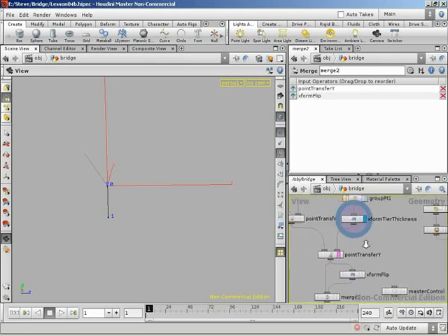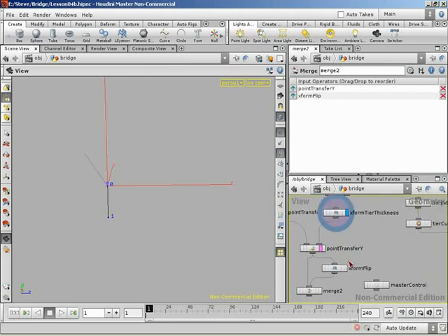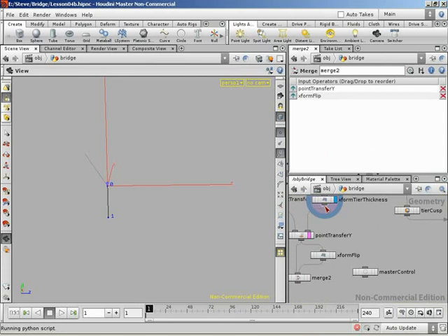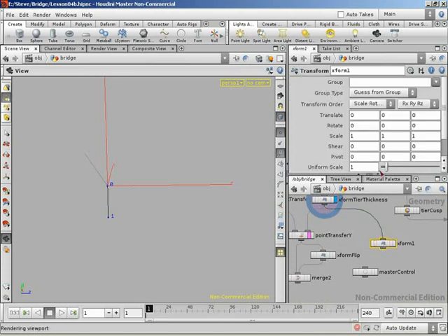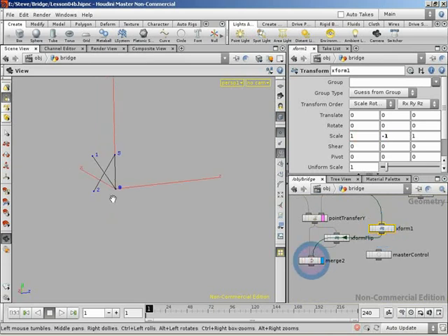So, yeah, this curve is actually going to work perfect for that end curve we needed, and he was right where we were working currently, which is great. So we can take this guy. I am going to branch off and wire him into a new transform, and with that transform I'm going to flip him in Y. So we can take our scale in Y and set that to a -1. And what that will do, that'll flip him up, which we can now take this guy and wire him into the merge also, giving us a crisscross pattern. Very nice, very nice. Awesome.